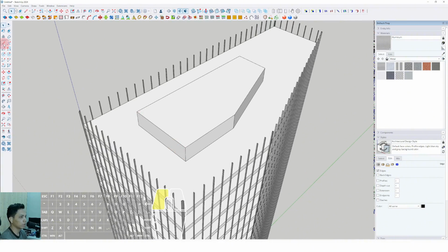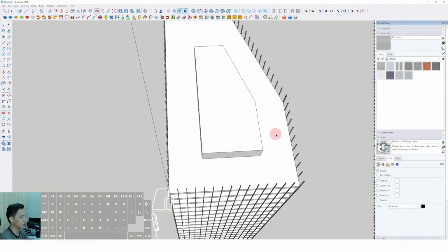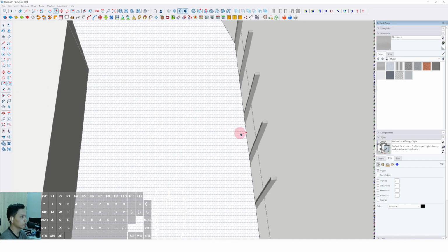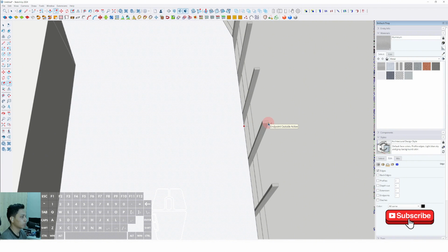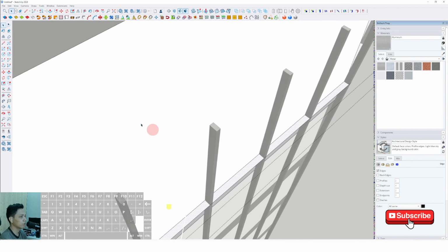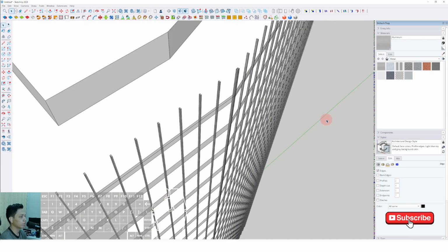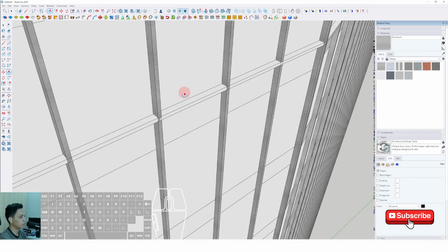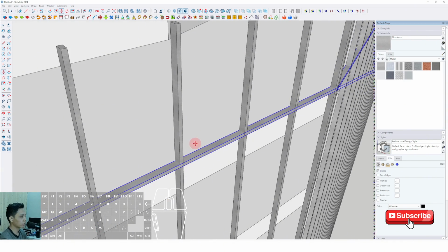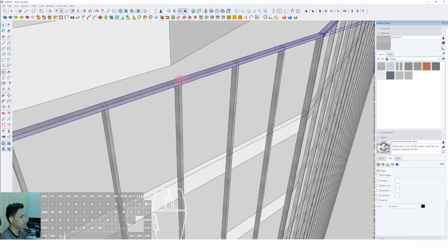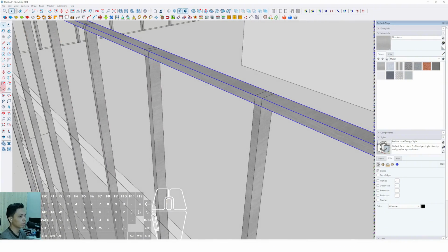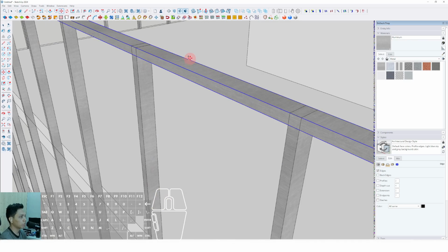We can make the line and just draw it, or we can just click this surfaces, click this plane, select offset tool, offset it outside, click to this position, then we can click this plane and select edit, cut, exit from the group and edit, paste in place and push it up around 100 millimeter. Triple click, right click, make group and assign the material, then select move, place to this position, right click and make component, just create.